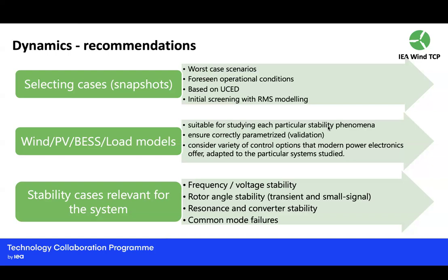That's very uncomforting for me, but go ahead. What you're really looking for here is to understand stability concerns with a given scenario, but also, from that stability concern, to understand what you need to do about it. Is it an operational decision? Is it something I can do by tuning the controls of several resources, or do I need to put a massive constraint back into my planning models that need to build more generation?